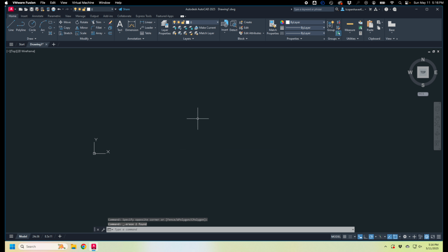So let's make something that we might actually make. And to do that, I'm going to need a rectangle. Let's draw a 4x8 Hollywood flat. So I'm going to type 48 inches to give me the horizontal and 96 to give me the vertical. I could also put that in, actually let me show you that.